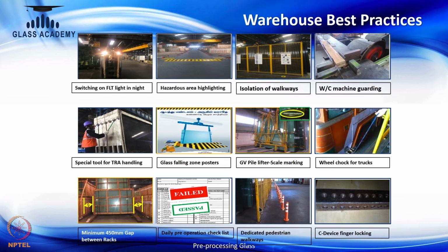Wood and glass are commonly found together in any kind of warehouse. So the wood cutting machine needs to be properly guarded, and only authorized people should be operating it. When you handle glass with an EOT crane, a lot of slings are used. We get to know about a lot of unsafe conditions where people's fingers get entangled between the sling and the glass bundles or glass crates.